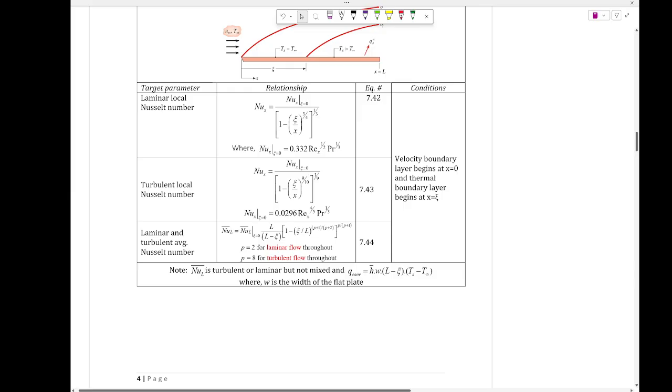The first thing: anytime you have a high difference in temperature, radiation becomes significant. An example is something you use pretty much every day, the oven. The oven is either a forced convection oven or a natural convection oven. If it's a natural convection oven, radiation actually dictates the heating, even though the cooking happens by convection, right?